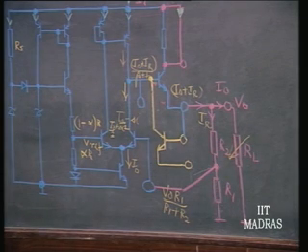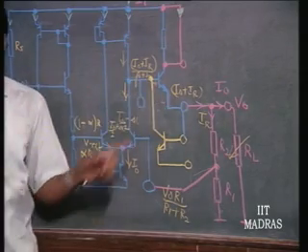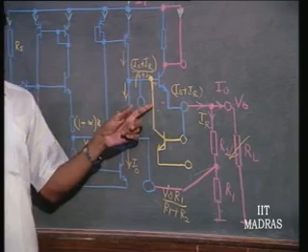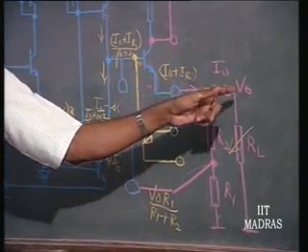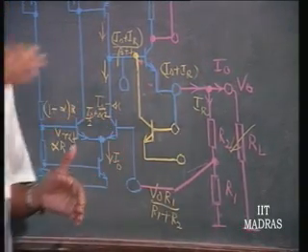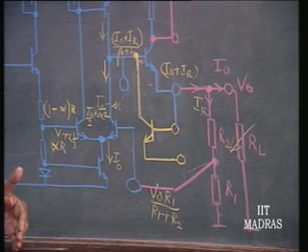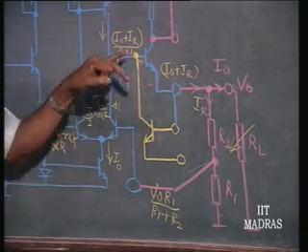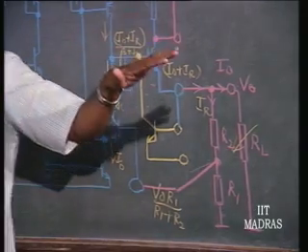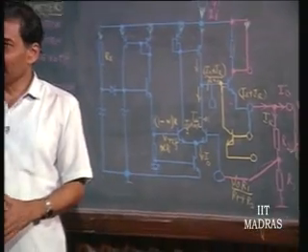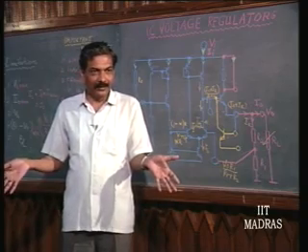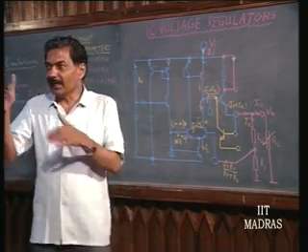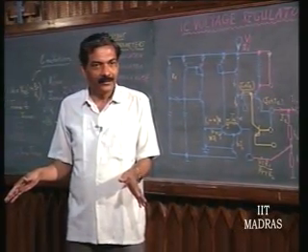So, this is one thing. So, if we put another emitter follower, this might be true. I mean, the way to do it is simply telling you that do not load me more, I am not capable of giving you that current, right. So, you put a current amplifier, that means the solution comes in the form of another transistor being connected in Darlington mode, right. So, that will reduce the demand on this, and for that load it will function. This way therefore, you can go on doing it until obviously the transistor says that is my maximum current of operation now. There is a maximum current of operation for the transistor itself. Do you understand that?